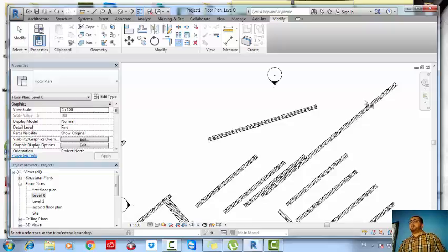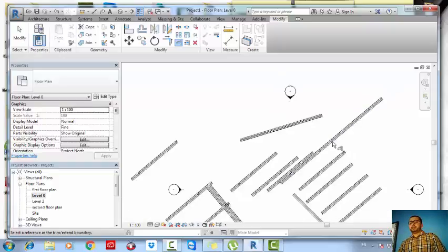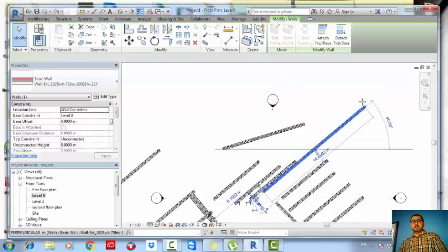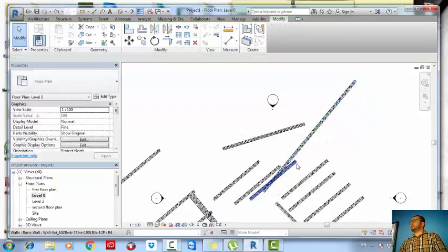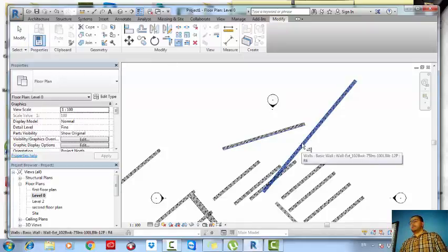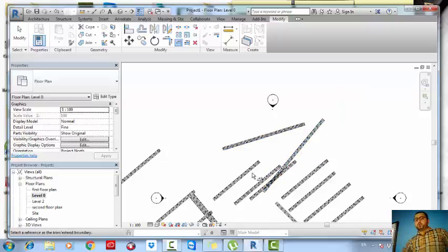Fine? Also the trim. Let's say that you have this wall like this, for example. And I want it to meet the extension of this wall. Just click again on this tool which is trim or extend, and click on the edge, then click on the part that you want to remain in your drawing. Click here. Fine? It's the trim and extend.